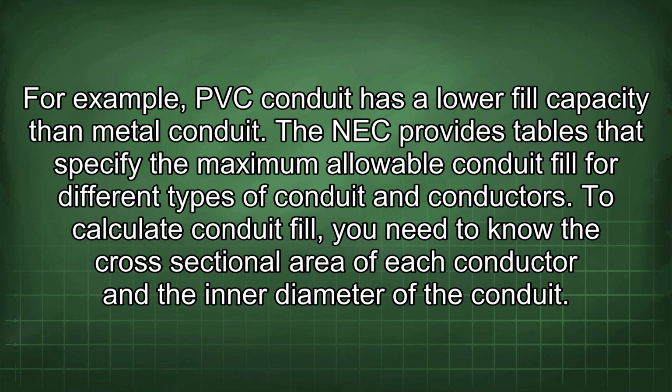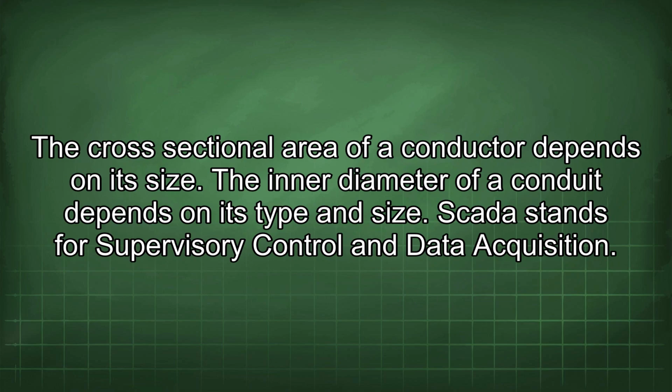To calculate the conduit fill, you need to know the cross-sectional area of each conductor and the inner diameter of the conduit. The cross-sectional area of a conductor depends on its size. The inner diameter of a conduit depends on its type and size.